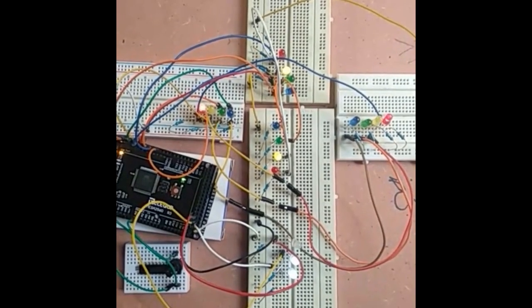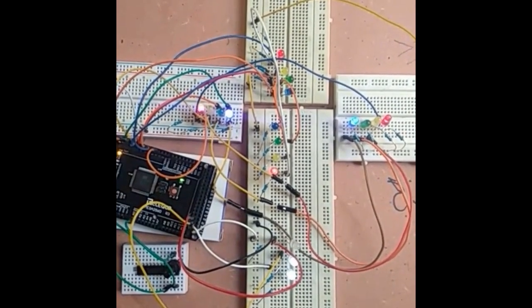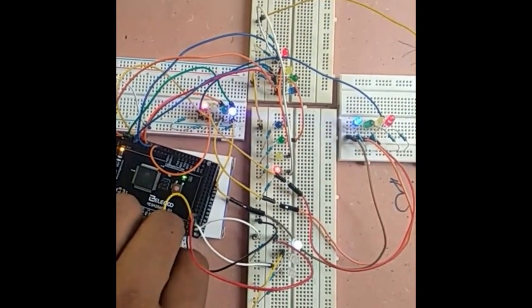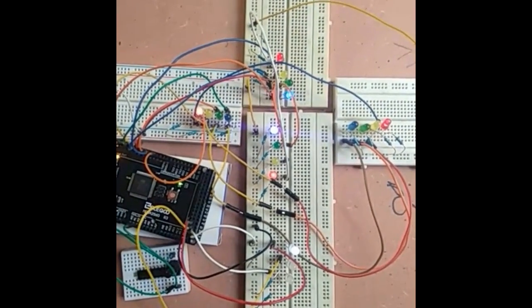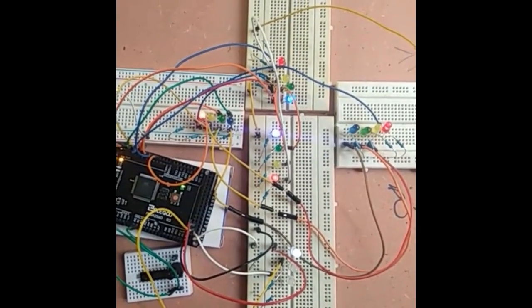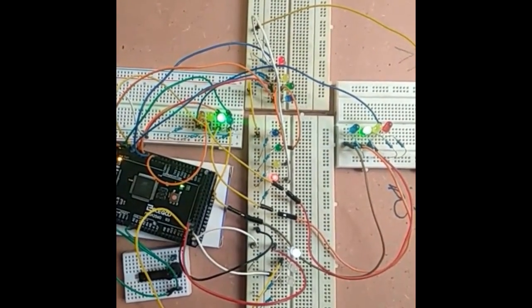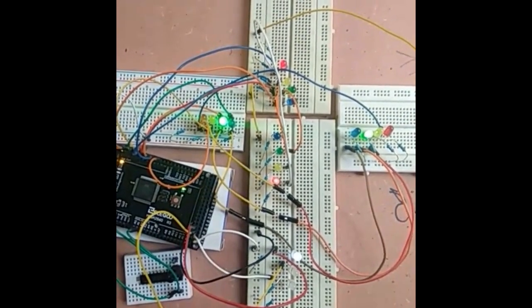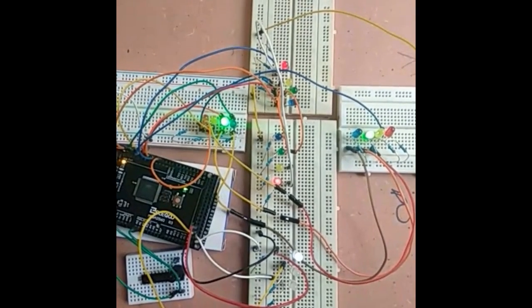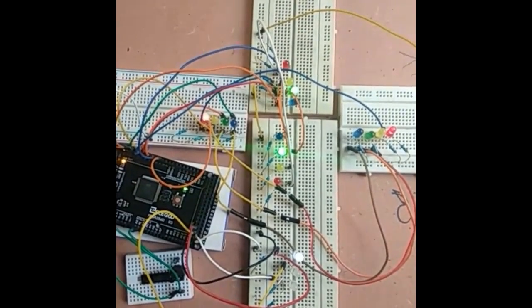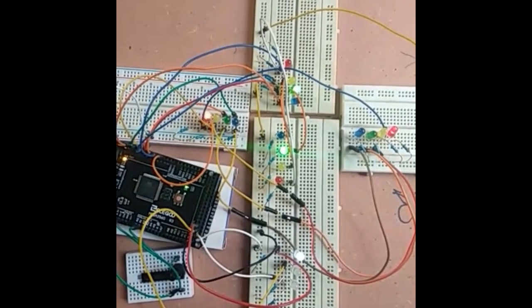As you see, the green LED took 9 seconds, after that 3 seconds for the yellow LED. Now increase it a little bit to make the multiplication factor a gain of 4. So as you see, this state should stay longer than the earlier time. Here the green LED should turn on for 12 seconds. After that the yellow LED will be turned on for 4 seconds. This is how we can change the delay between the states using a potentiometer.